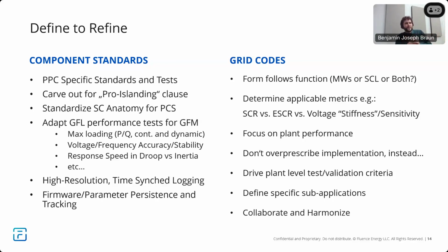Short circuit ratio is definitely a bit of a static measure. You have short circuit level, as they've used in the UK, but that gets more at the actual fault current and not necessarily how you're dynamically stabilizing the voltage in a small signal sense. You can easily calculate it, and they have a line saying, based on your voltage drop, how much short circuit level should you provide.